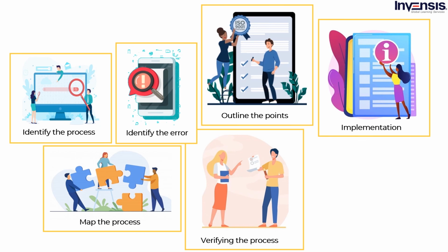Implement a system. Develop and select the Poka-Yoke device or method and implement it into the existing process. Ensure that operators are aware of the changes being made and how they will be affected. And of course, it's also important to ensure that you gain some valuable knowledge and experience from those situations where you run into errors. And then, you'll obviously also need to make sure that this information gets properly used and doesn't just end up in some random archive.